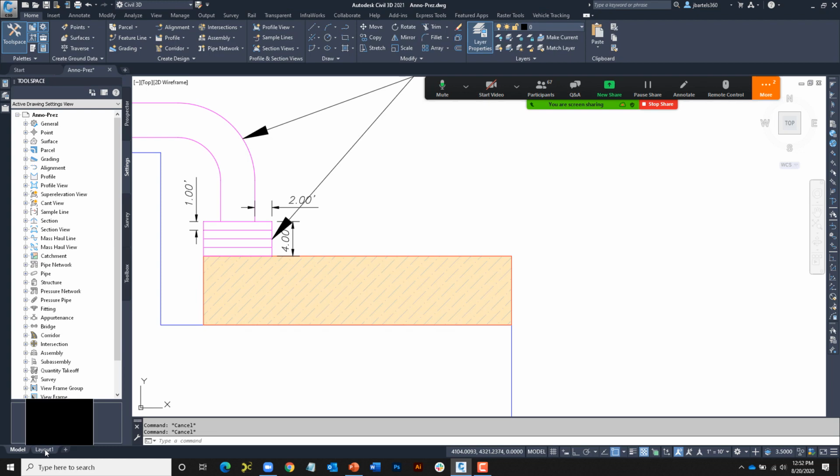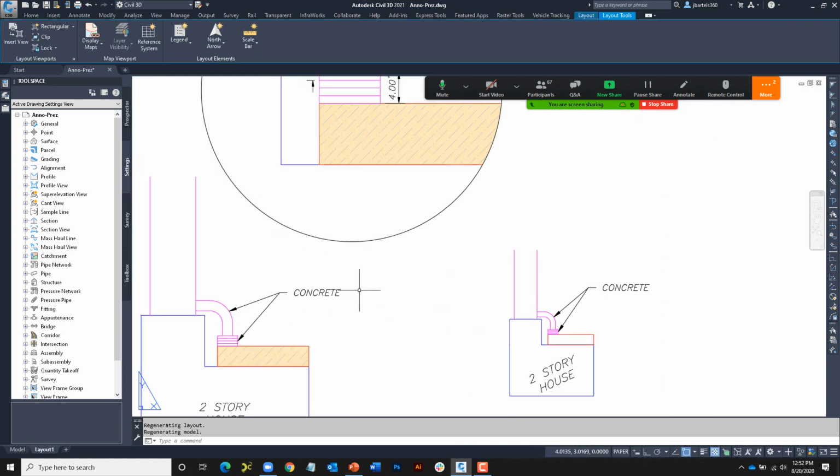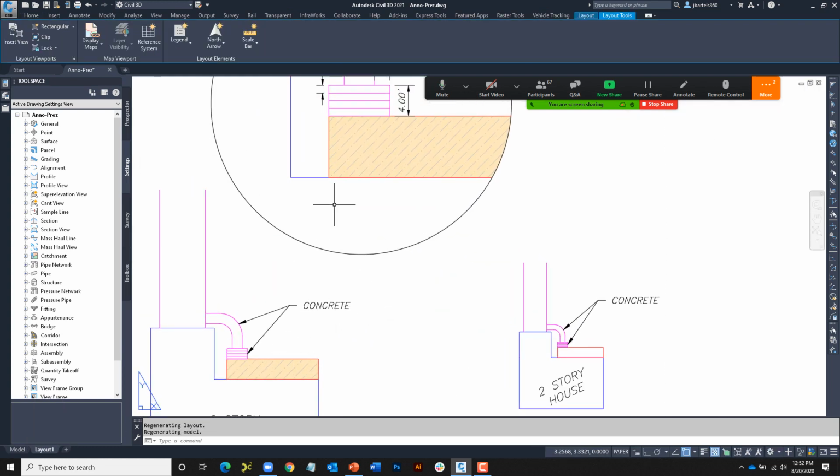Immediately after doing that, I'm going to go to the Layout tab, and you can see that hatch shows up in both views, and it is sized the same regardless of the scale of the viewport. So if you've ever hatched things before and you have a legend that represents what all your hatch patterns are, sometimes that legend has to be scale dependent because as your geometry gets larger or farther away, hatch patterns look larger or smaller. Using Annotative Hatch, the hatch will always be appropriately sized regardless of the viewport where it's placed. And all of these items, they're honored through an external reference.